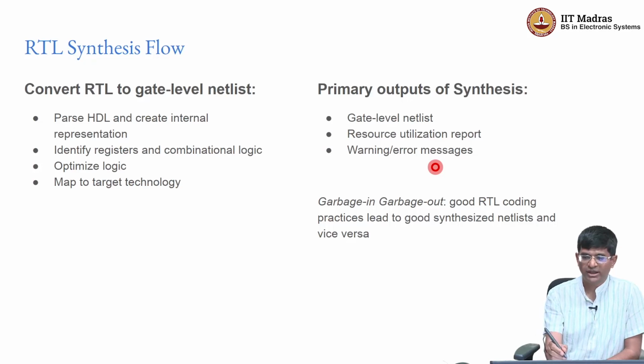As with any other kind of programming, the idea of garbage in, garbage out always holds. If you have not written code keeping the principles of RTL based design in mind, it is almost certain that you will get syntactically correct Verilog code which may even pass your simulations, but which will not give you a netlist that actually does what you want. So please keep that in mind. I will be repeating it multiple times throughout the course. Your goal is not just to write Verilog, it is to design hardware. So you need to think about what your hardware should look like and then figure out how to write the code that will give you the design that you want.